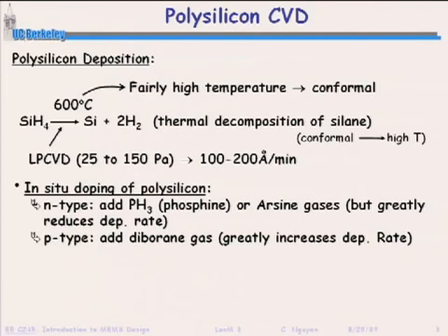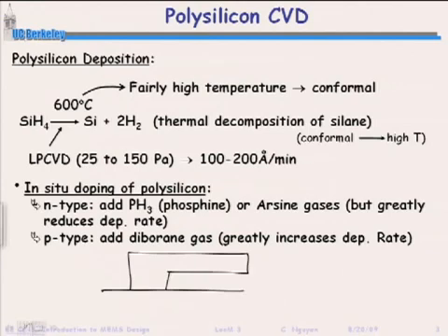And if you have a high enough temperature, then since the adatoms can move all around, you can get very conformal depositions. What I mean by a conformal deposition, we talked about last time, is that if you had even a MEMS structure that looks like this, a conformal deposition would be one that can encase this MEMS structure, not only covering the sidewalls where its thickness is the same everywhere, but even getting underneath structures like that and going into little crevices.